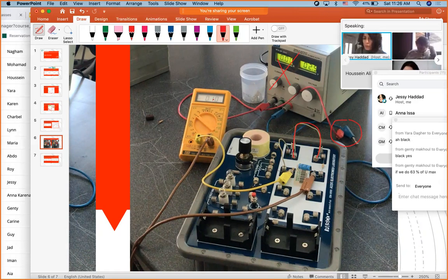Also, I need to start from Umax, which is 2.9, down to 37%. So 2.9 times 0.37 will give me 1.07. So I should time between 2.9 volts down to 1.07 volts. How do I start from 2.9?